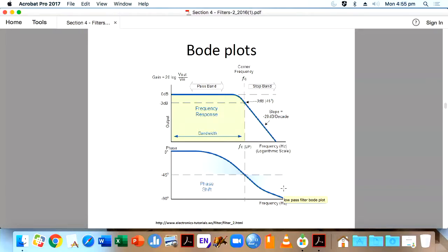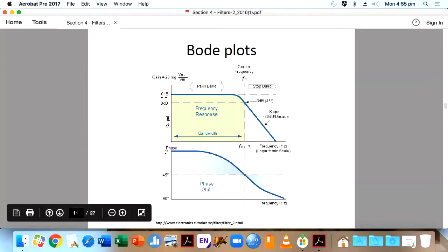So if you get negative feedback, the negative feedback will become positive feedback if you get a phase shift of 180 degrees. We will study that later. That is the reason when you design a filter, we will be plotting gain versus frequency and then prove that it is a low pass filter with the cutoff. Then we will also plot the phase with respect to the frequency, because we want to see whether the phase of the signal is inverting or not.